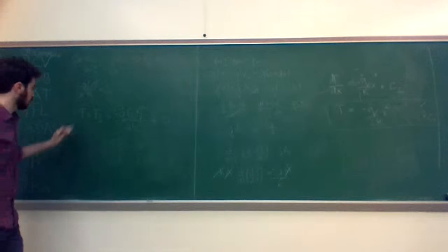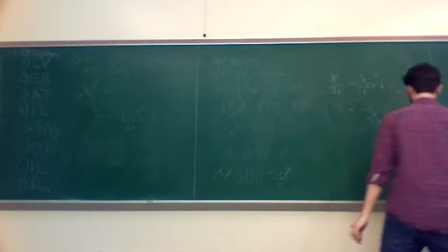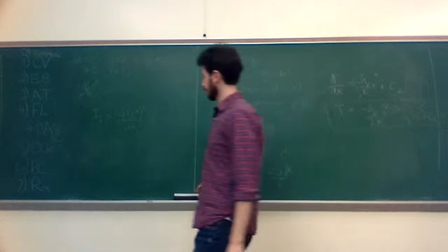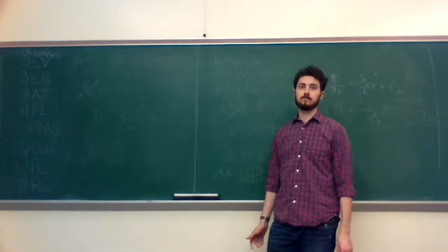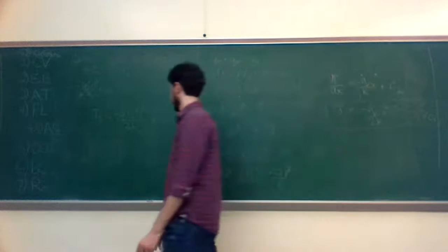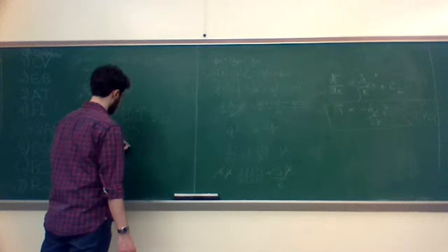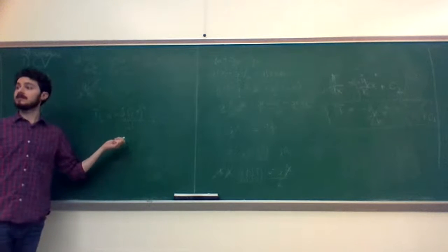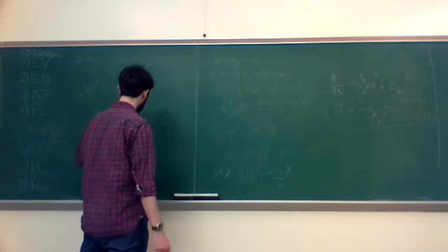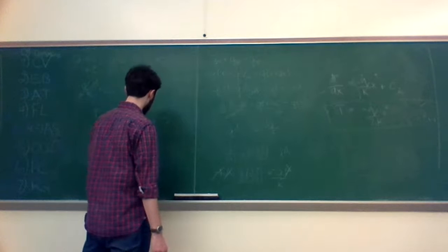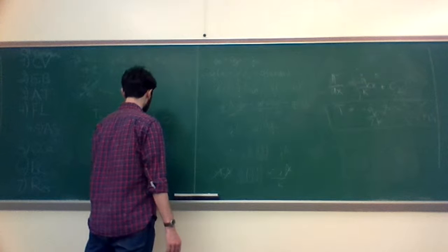So, I don't even want to keep that up. So then what's C1? You just move the first term over, you're done. C1 is exactly equal to, because all of these are constants, basically, right? This is all stuff that we know. So C1 is just TS plus q dot L star squared over 2k.